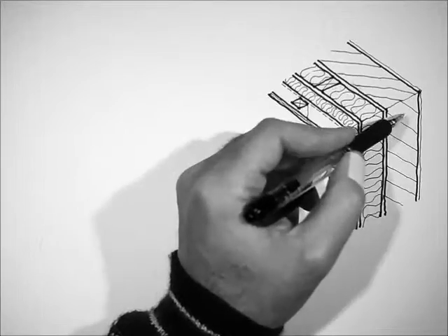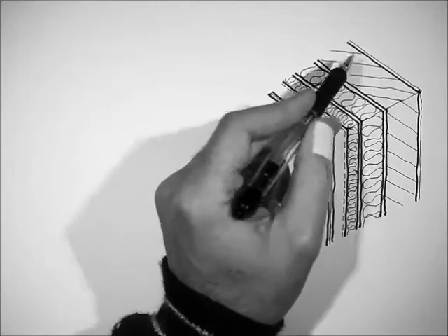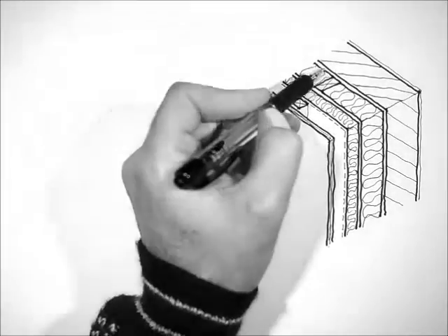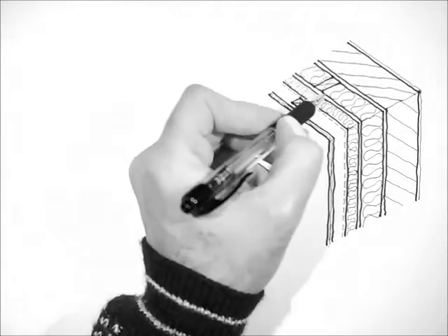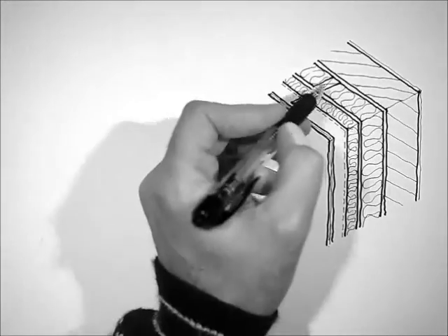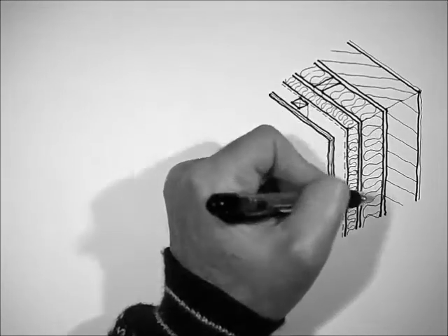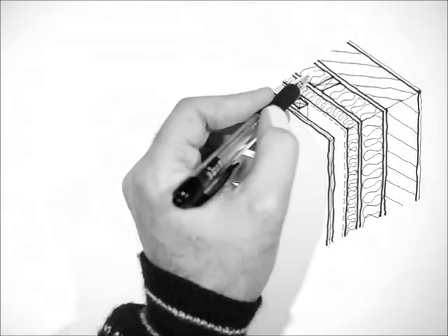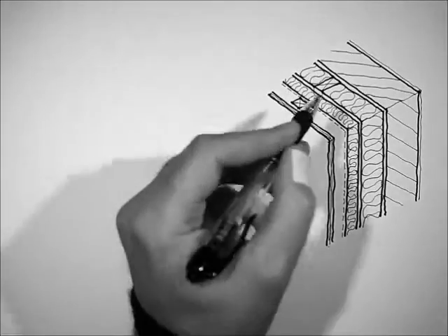It could be masonry, there could be steelwork, columns and beams in that same zone. Outside of that masonry there are vertical studs creating an insulation zone, and this could be a low efficiency insulation like mineral fibre.